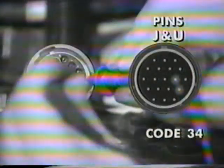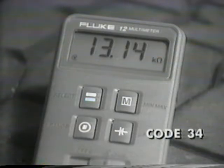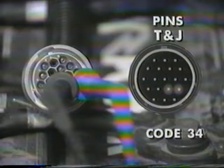Reconnect the harness to the throttle position sensor. Disconnect the vehicle interface harness connector from the shift bar cover and take the reading between pins J and U, which connect to sensor terminals A and C. This measures sensor resistance, and your reading should be between 9 and 15 k ohms. With the probes between T and J, move the throttle slowly.